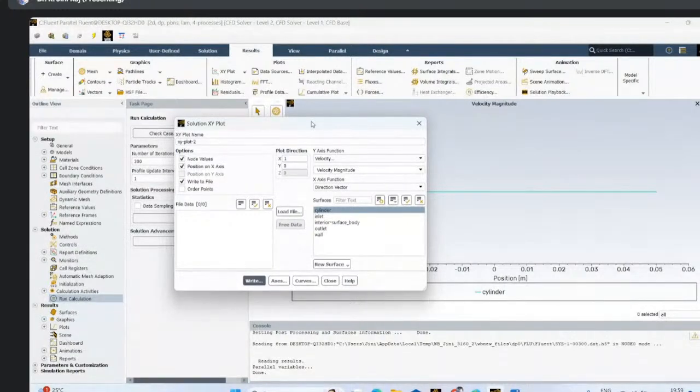One cylinder, and behind that one more cylinder, and the same control volume like this. So you will get an idea how the flow behaves with two cylinders. If you want, you can go with three or four cylinders also, but at least do this one. Make the control volume in such a way, do the same analysis, and check for different velocities. Now I have given 2 meter per second, but you can check for different velocities also.